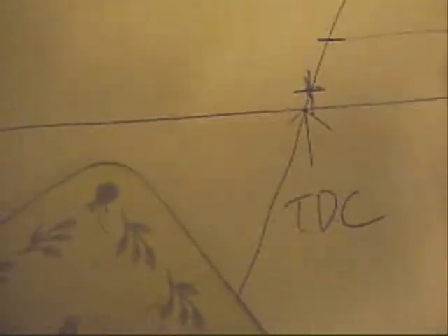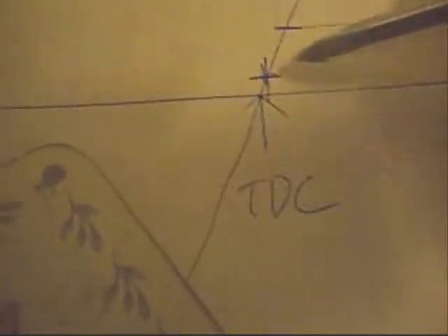However, the trigger system that I'm creating allows me to set two different points, that is the turn on point and the turn off point. So, for example, on mine I can have a turn on point that is literally just past top dead centre, and a turn off point up here.